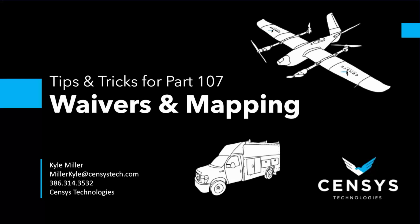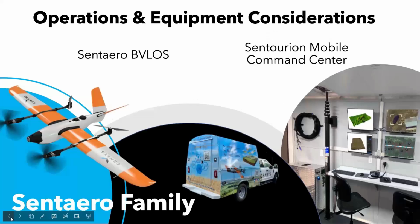What payloads do the Census Tech fixed-wing drones accommodate, and how easily are they swappable? So our payloads are all field swappable. They all come in a universal payload box. Backing up to a picture of the plane, underneath the fuselage in the center, every payload has its own box that slides in and out of the bottom of the fuselage. So they're all field swappable. However long it takes you to undo 4 thumb screws is how long it takes you to swap a payload.